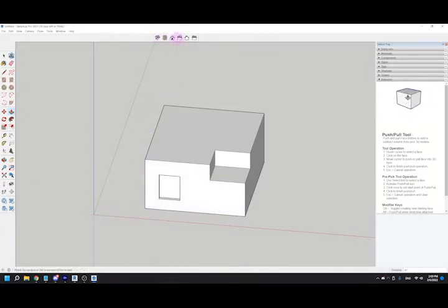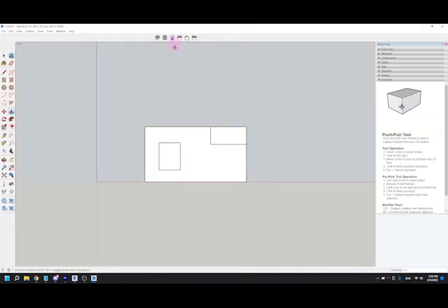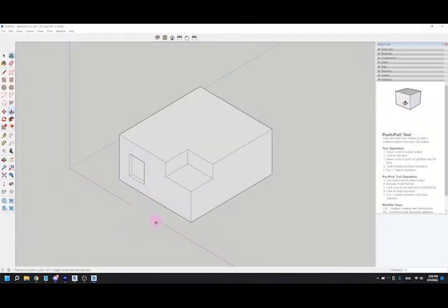The reason why I also opened up this view toolbar is this then allows me to quickly just snap to an isometric style drawing versus from the top, the front, any side that I want to, and turning that projection off kind of just gives me these orthographic views that we were focusing on with our elevations or with our object models much easier than if I had to ever draw anything by hand.